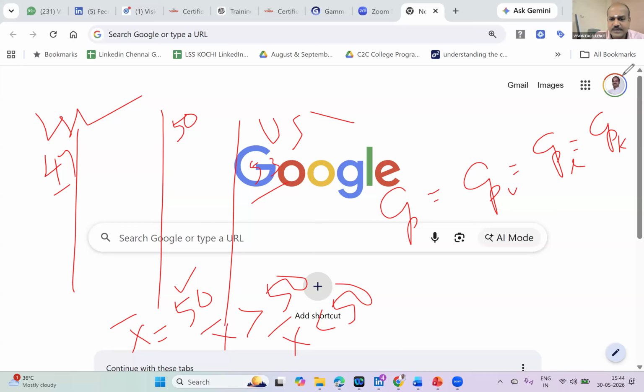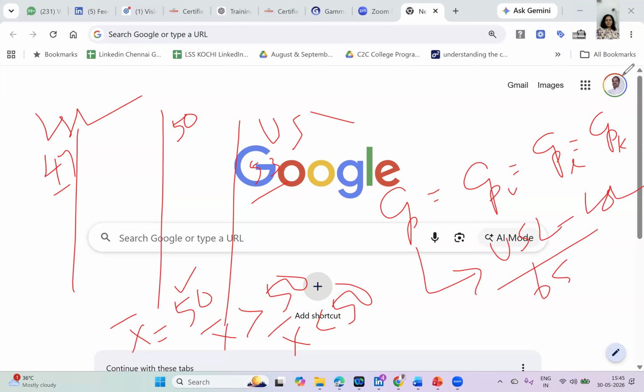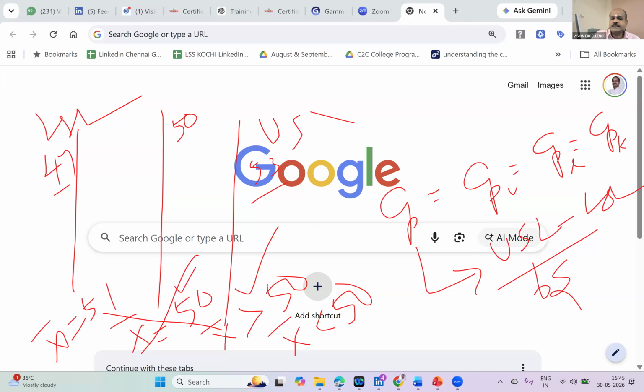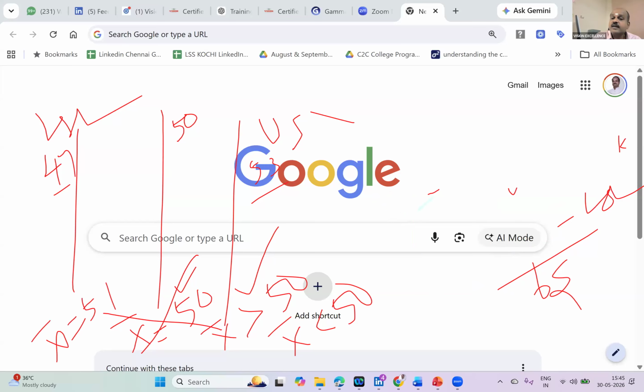I think the one that can be calculated easily is USL minus LSL divided by 6S. This is the formula. You don't have to change the formula. But the formula may change if this condition is violated. Let's say this is the situation. Your X bar may be, let us say, 51. Now, what is the condition? X bar is more than 50 or less than 50? More than 50. Now, all these conditions will be violated.